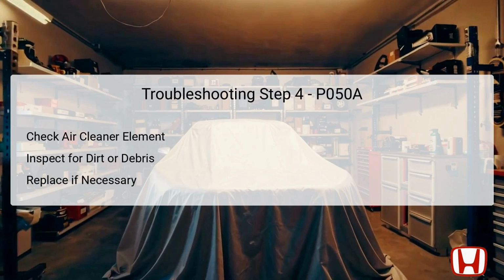The focus of this step is the air cleaner element. This component filters the incoming air that enters the engine, protecting it from dirt and debris that can lead to damage. Inspect the air cleaner element for any signs of excessive dirt or blockage.